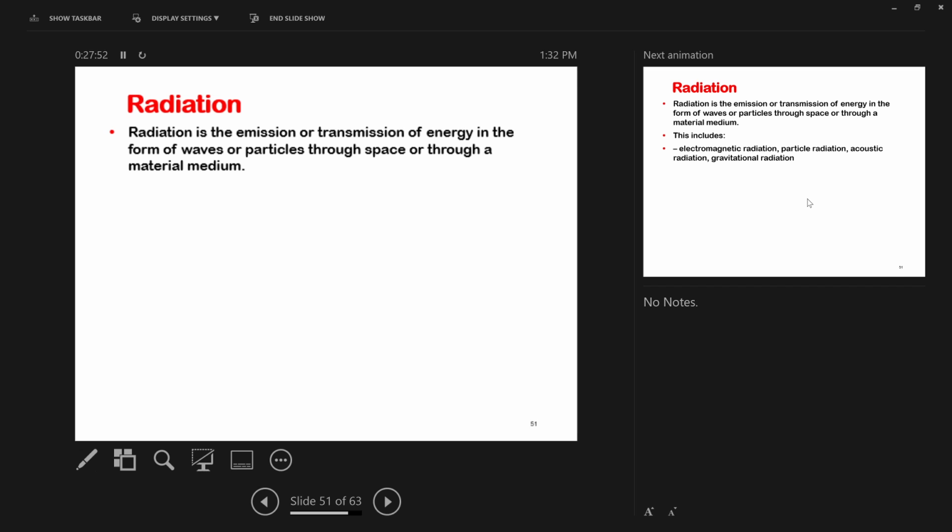So that's the idea here. You think of the solid as a solid slab, right? A continuous surface, but in reality, it is not a continuous surface. It's just different molecules that are bonded to each other. So the energy can be transferred through radiation in a solid medium, but the conduction inside the solid is so dominant that we don't really care about the radiation, right? It doesn't really matter inside the solid. So radiation is way more dominant in a vacuum or in gases.